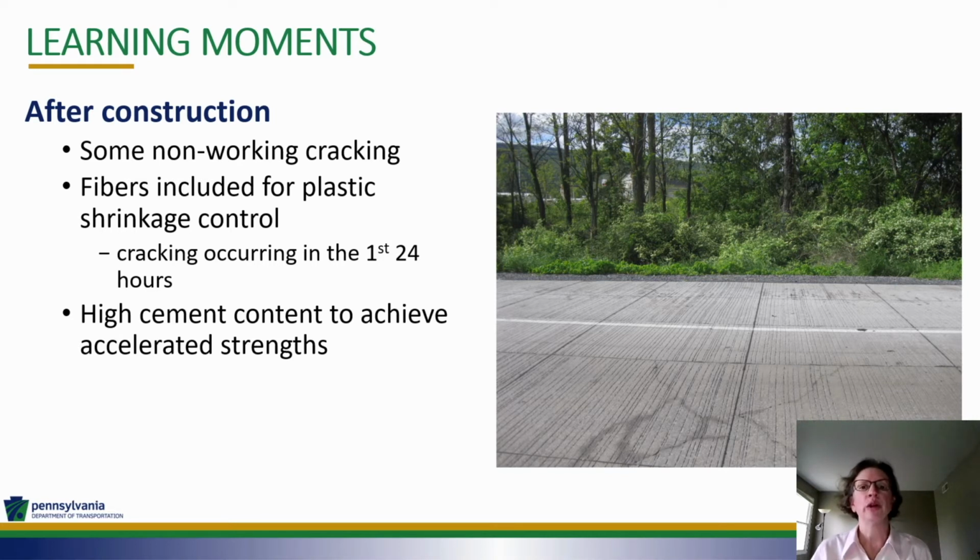The specification required a minimum of 650 pounds per cubic yard of cement, but did not specify a maximum. 900 pounds per cubic yard were used in the mix design to achieve the required minimum 3,000 psi in 24 hours, and in fact achieved just over 4,000 psi in 24 hours. Contrast that with accelerated patching, which was limited to a maximum of 800 pounds per cubic yard to achieve 1,500 psi in 7 hours.